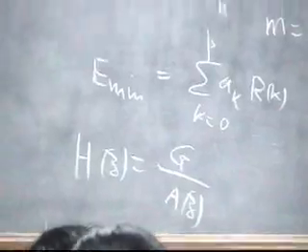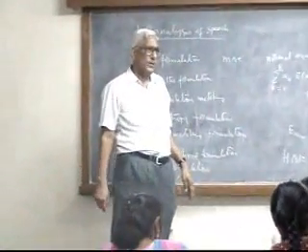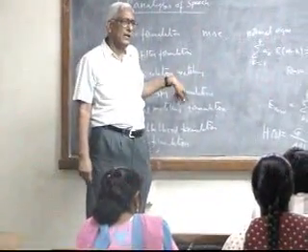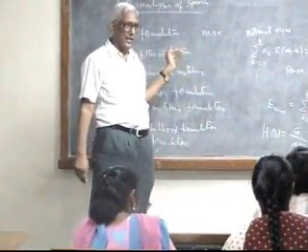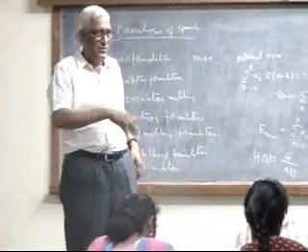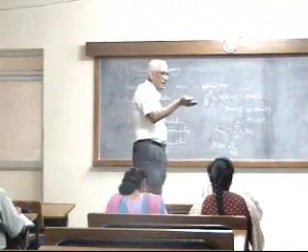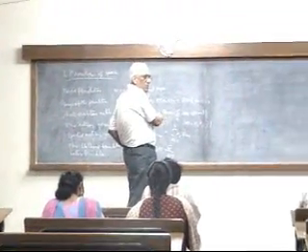Notice that this is only G by A(z), or 1 by A(z) is also fine, because G can be taken care of by the error itself. So you can excite this system, which is 1 by A(z), by that error, and G is automatically taken care of. On the other hand, if you normalize the error by its energy, then G should be put back here.